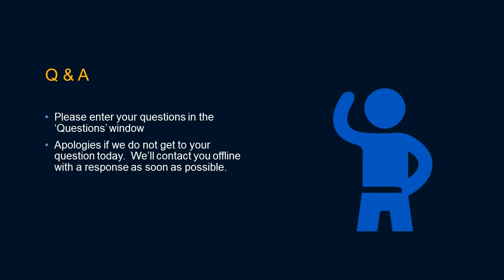What you'd find is that on those type of devices where jitter becomes a problem, they'll say, well, here's my K factor, but it's only valid above this specific flow rate. And then under that, they may not give you anything, or they may give you some kind of changing nonlinear K factors to try to reduce the effect that jitter has. So most of the time, hopefully, you wouldn't have to worry about that. But if you start seeing specifications that require minimum flow rates, you really ought to start paying attention, because it can be a problem if the device can't handle it mechanically.